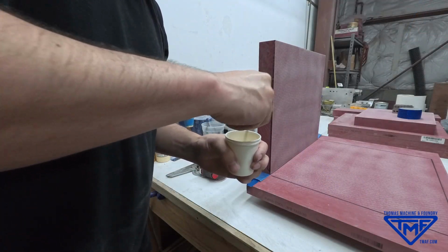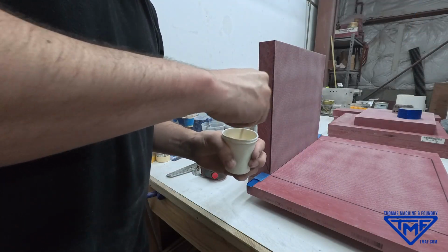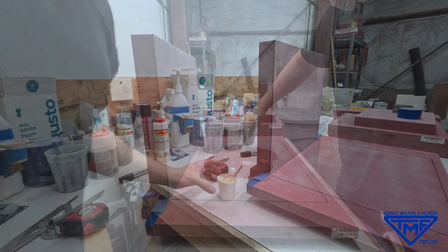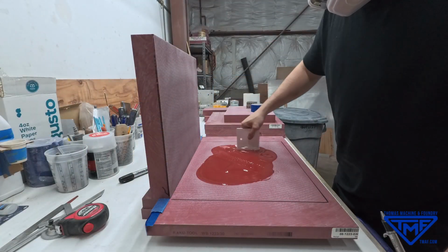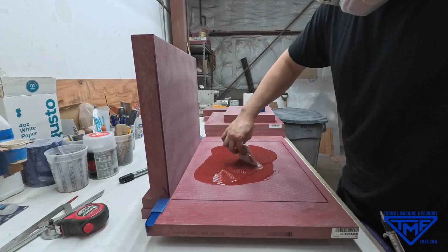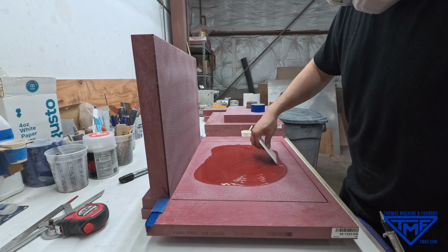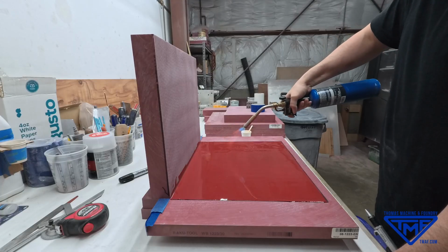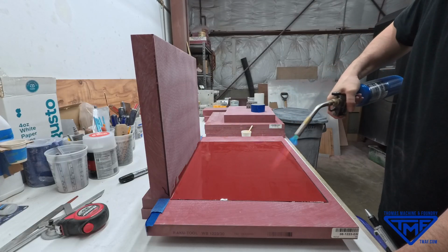is ready. The adhesive used for this process is a 2-part epoxy. It provides a strong bond, but also gives enough working time to carefully position each piece. Depending on the material and the conditions, the epoxy takes roughly 2 to 4 hours to fully cure. The glue is applied to the marked area, then the heat from a torch bursts any small air bubbles created during the mixing and spreading of the adhesive.